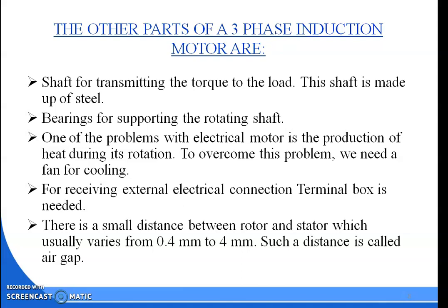Otherwise, it may lead to damage of the windings, either the field or the armature. Clear? So, we use this fan so that there will be reduction of heat. There will be elimination of the heat which is being produced during the whole rotation or operation inside the induction motor. Next,